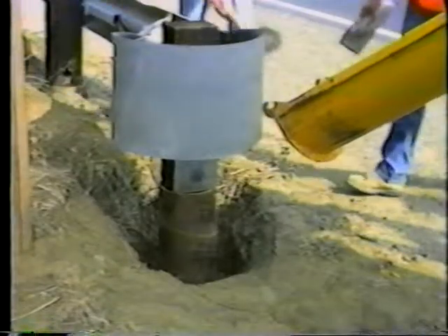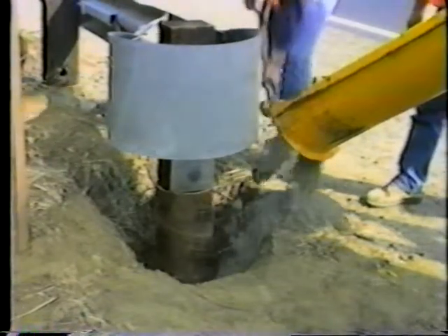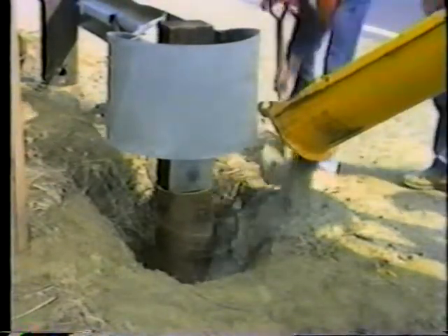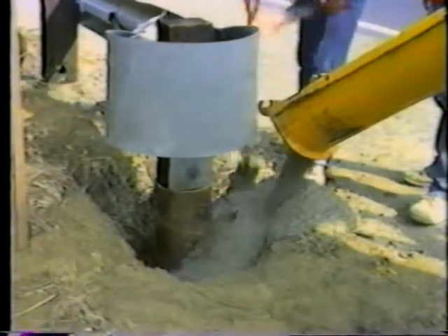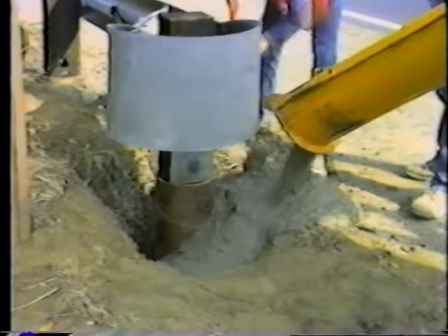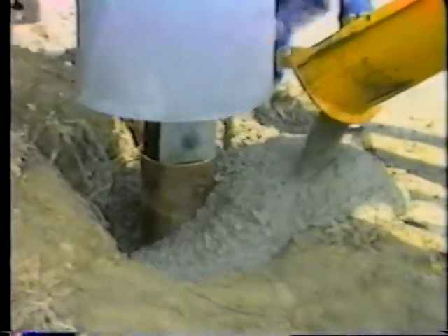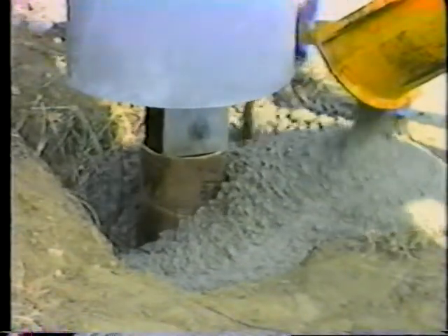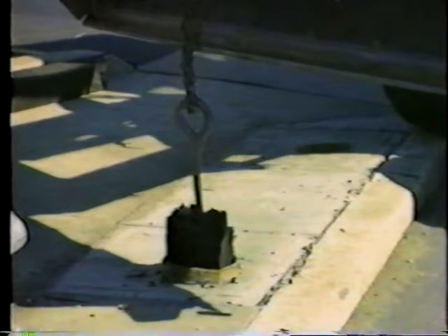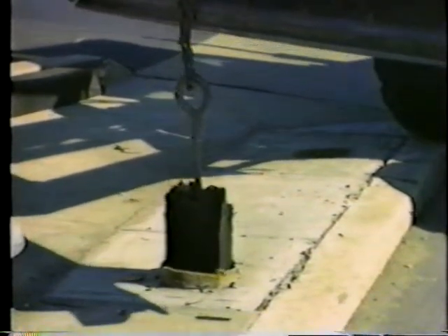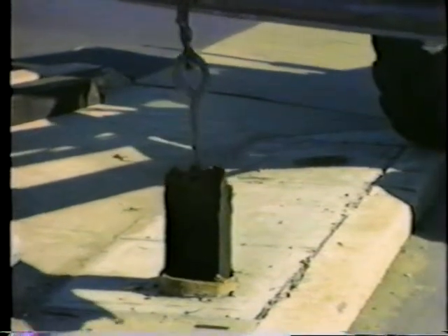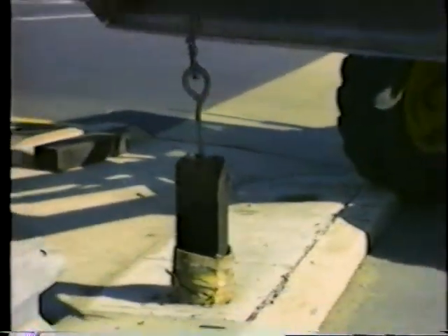To ensure that the first and second posts of the system break away and are not pushed over when impacted, they're set in concrete footings of at least 3-foot depth. The surrounding soil must be stable. A loose sand will not work. Removal of broken stubs has created some problems, with several solutions being worked out. A styrofoam sleeve and a steel sleeve with soil plates are 2 different concepts available.